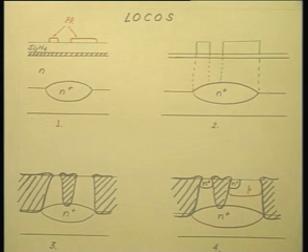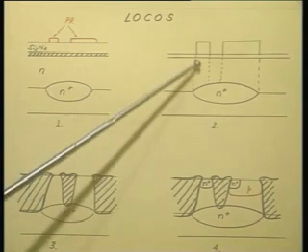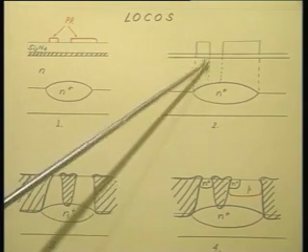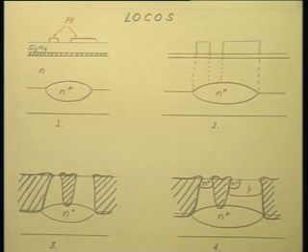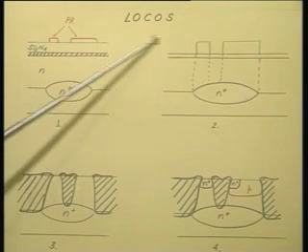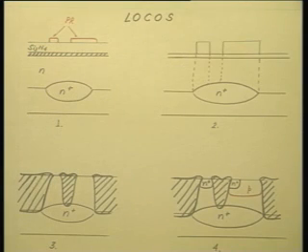So, instead of that, what is done is one additional step, as I have shown by this dotted line. You etch a little bit of silicon, that is, whatever is the oxide thickness you want, you etch it down by about 0.55 times of that.